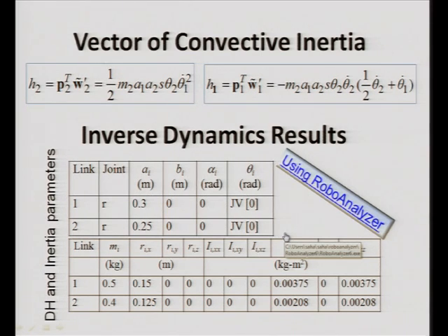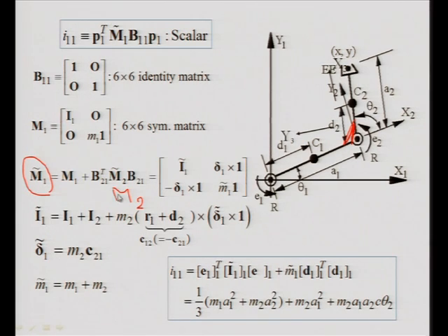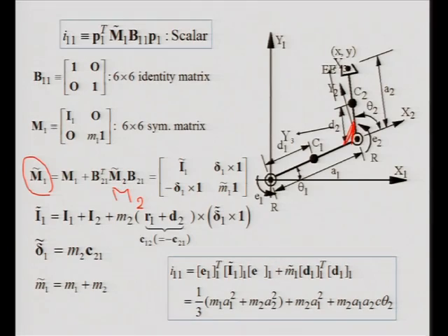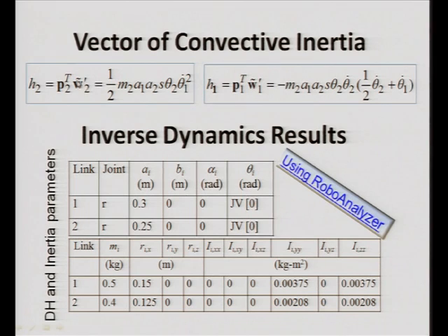Now, proceeding in a similar manner, one thing I wanted to emphasize here is that this is also recursive. Everywhere we are trying to get a recursive relation. So, even to find out the elements of the inertia matrix, I am able to derive a set of recursive expressions. When I calculate H, I also have a set of recursive expressions, which I showed in yesterday's class, and then I computed the results.